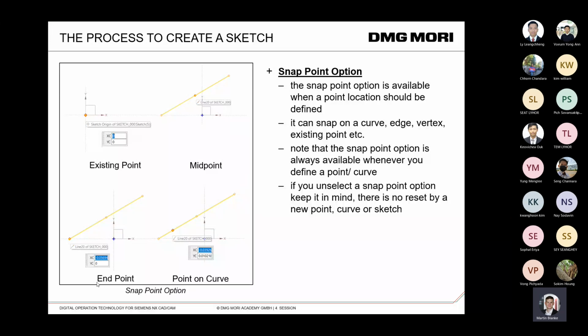for example, you don't want to have the possibility to click the midpoint, so you unselect the midpoint, then please keep in mind there is no reset by a new point or a new curve. Or if you create a new sketch, the midpoint is unselected as well. So this is a very important point, where, as I can tell you from my experience,